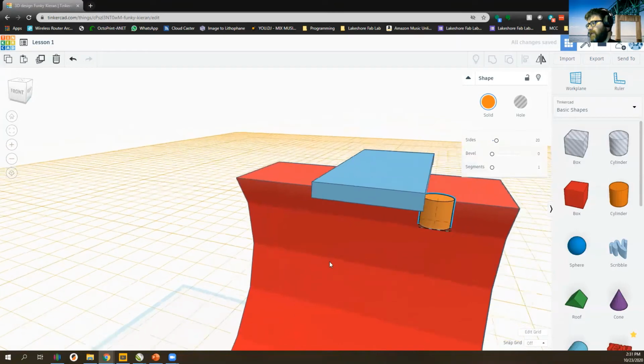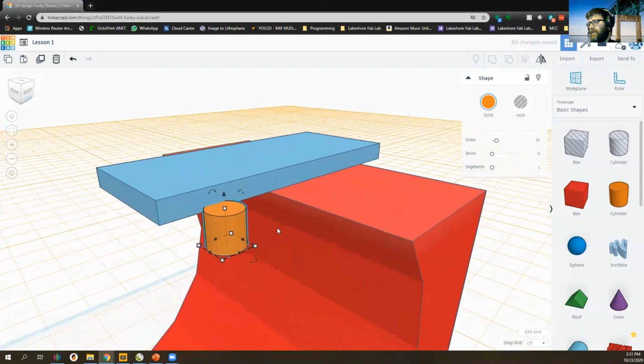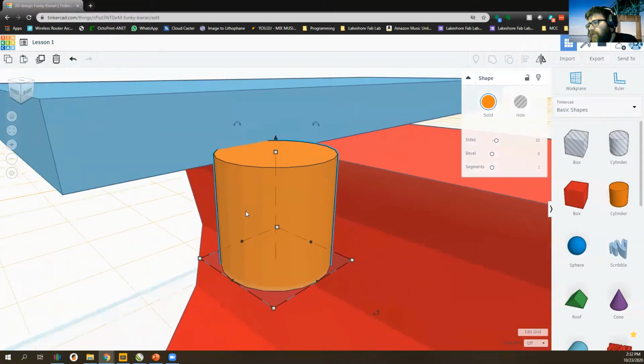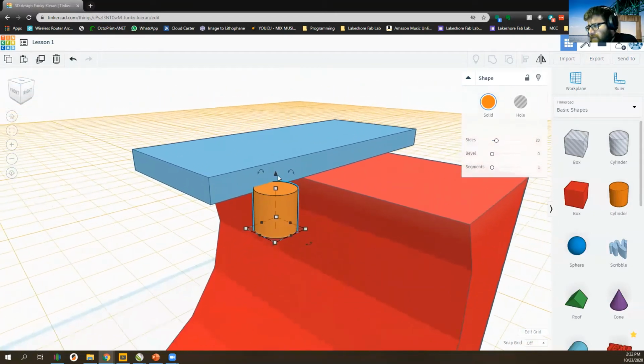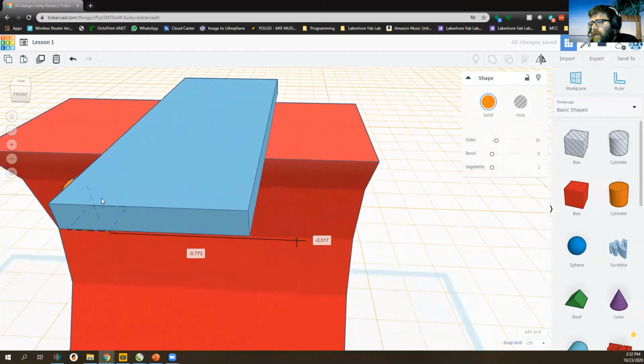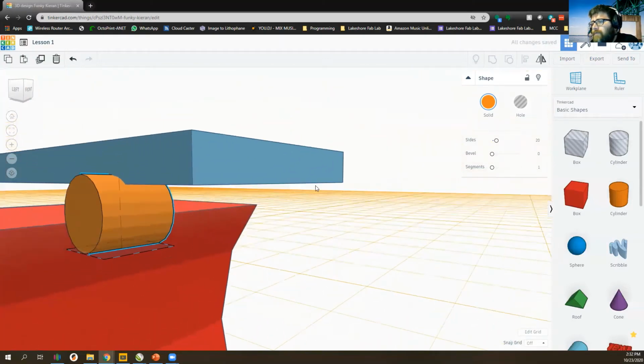All right. So let's say I want to rotate. So I'm zooming in to get a better view, but let's say I'm out here and I want to look in there closer. I can actually click on this fit view to selected shape button over here under the house on the left, and it will zoom in so I can better look at that object. I'm going to rotate this guy so he's laying the other direction. And we're going to set him there on the other side.